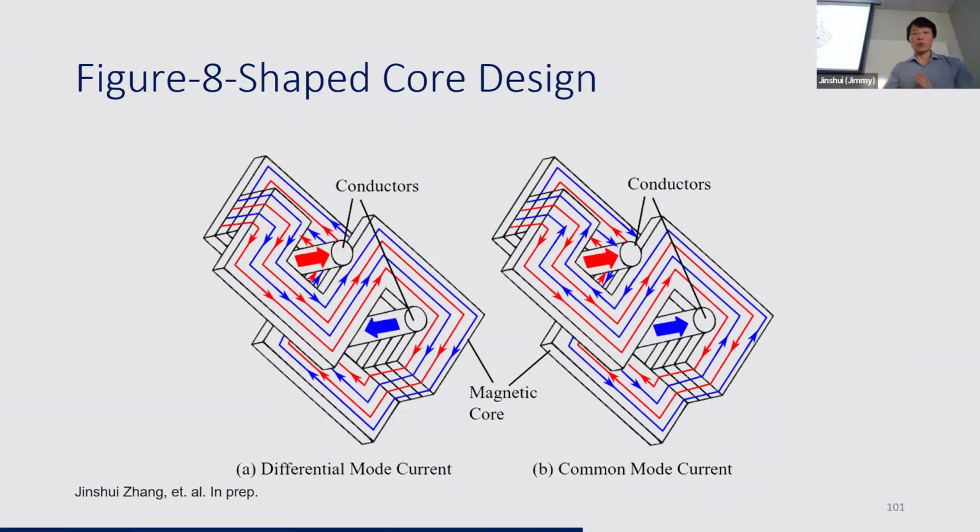In this design, we are not winding the wires onto the magnetic core. We're actually winding the magnetic core onto the wire or busbar or any other conductors. So in this way, we get a clip-on ferrite that gives us differential mode inductance without touching the wire at all.